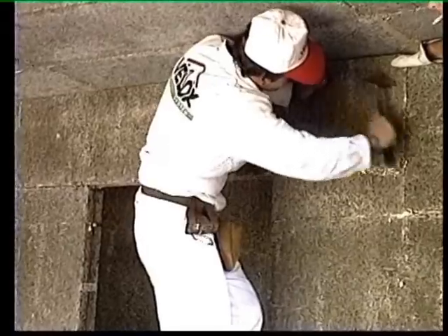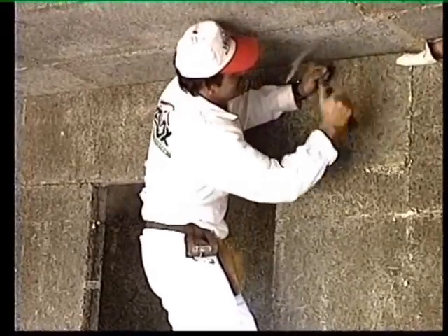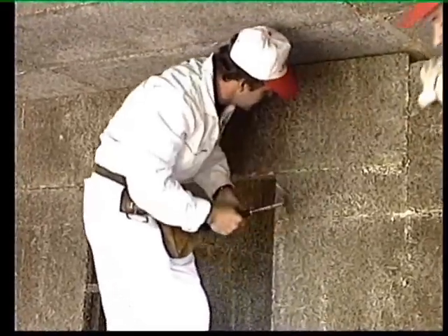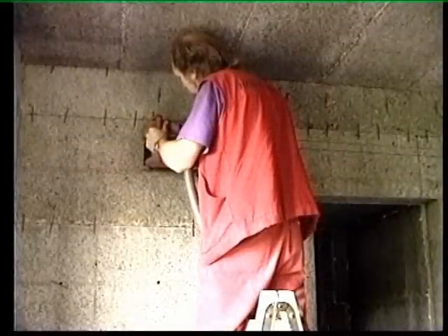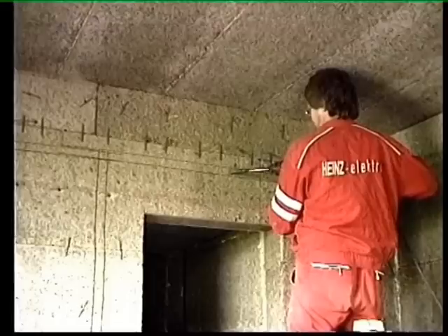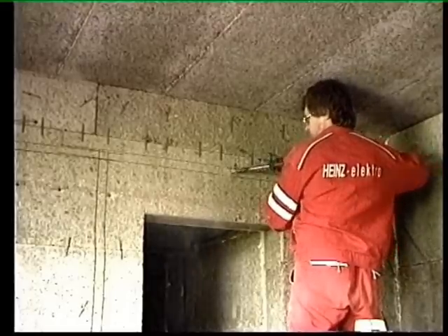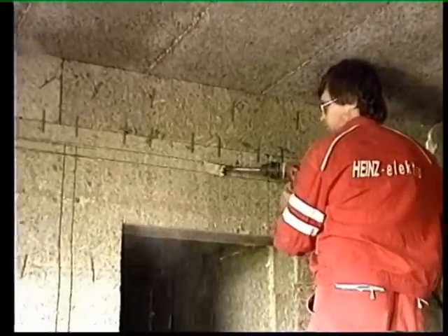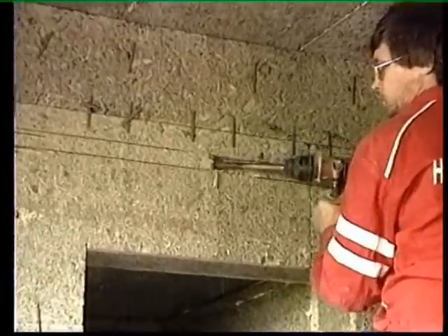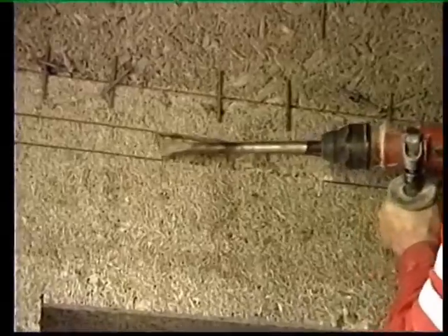As is the case with load-bearing walls, cutting boards for partitions is simple. A row of boards is installed beneath the ceiling, and the joint is filled with the bonding material. Thanks to the fast drying time of the bonding material, the partitions quickly achieve their final high level of strength. This enables grooves to be cut immediately for electrical wiring.